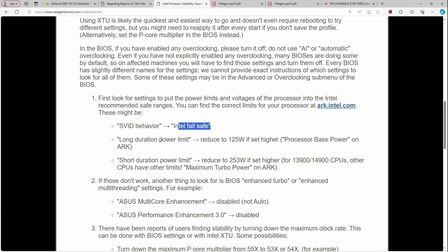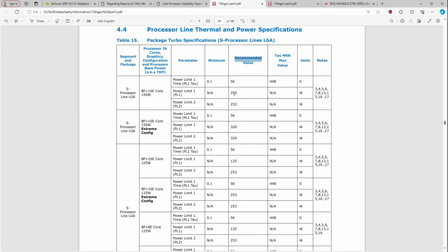And then kind of an interesting wackiness is if you are at that 100 degree temperature limit, 100 degrees Celsius at 1.3 volts and 1.2 volts will have different amounts of current draw, right? Because if you have a 300 watt cooling system and the CPU is hitting 100 degrees Celsius, then at 1.2 volts, these Intel chips, if you have enough cooling, you can get them to pull like 400, 500 watts.